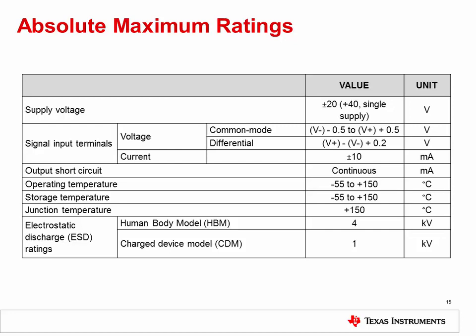The absolute maximum ratings given in a device datasheet describe the worst-case conditions that can be applied to a device before damage occurs. Maximum supply voltage, input current, and temperature are given. Notice that the maximum input current is given as plus or minus 10 milliamps. This is the limit for most devices and is based on the maximum continuous current that the ESD diodes can sustain.